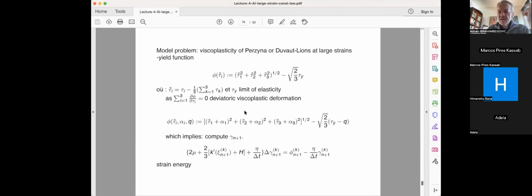If I want to extend this beyond perfect plasticity, which is what is here, I include all kinds of hardening. I simply add on top of every tau the corresponding back stress alpha i, which follows the same rule that I just explained, sharing the same eigenvectors and so forth. This gives me a modification of how the origin of the elastic domain is moving.